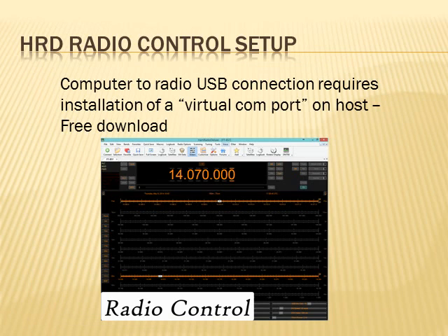One other point of information is that when you're using this radio control software, it needs a COM port, and since over the remote we don't have a real COM port connection, we need a virtual COM port loaded on the host. That is a free download, and you can download it from Kenwood or whatever vendor is available for your particular computer.